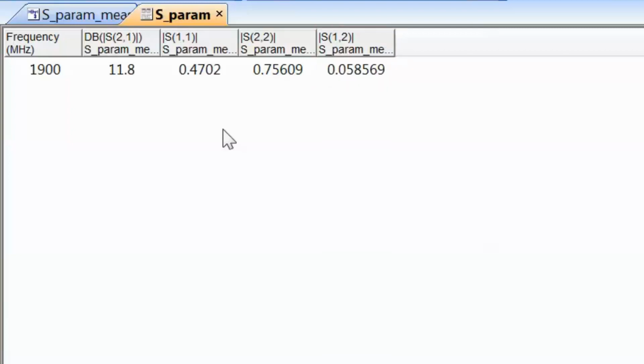And this means that whatever you connect at whatever side is going to affect what's going to happen to the currents and voltages on the other side. And hence, because as we know impedance is the ratio of voltage and current, we'll see a change in the output or input impedance depending on where we've connected a termination.